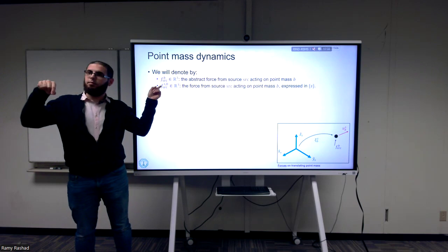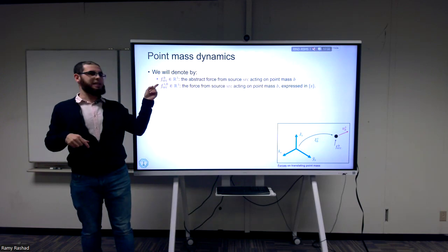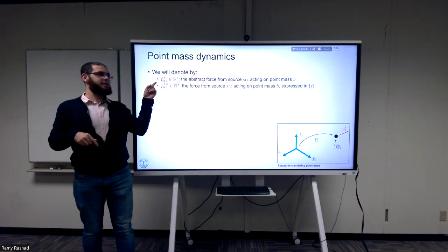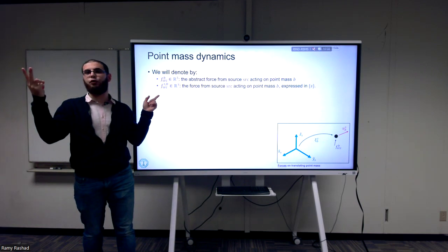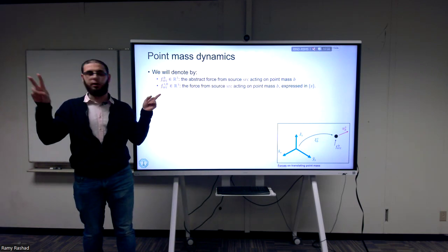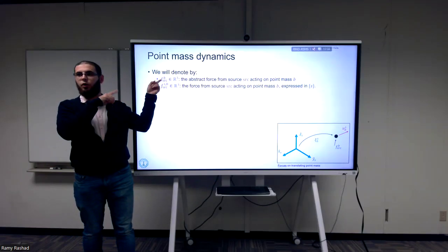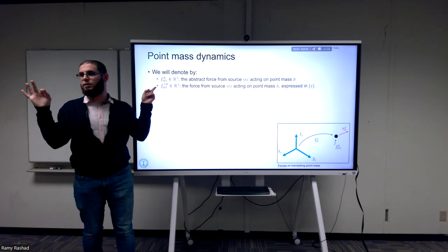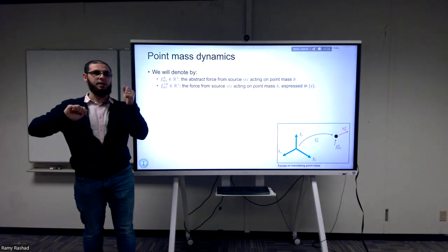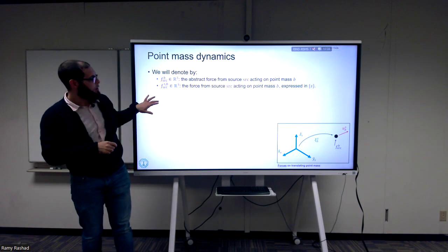It's applied on the point B, and we express it in frame S. A force, a torque and a wrench will always have only 2 indices: one up on the right, one up on the left. So we don't have 3 indices for forces, torques and wrenches, like what we had with velocity. Velocity was always something with respect to something expressed in a third thing.